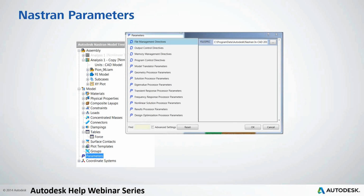Those are found on the model tree down at the very bottom. You right-click and you can edit, and it's going to pull up the parameters there. So it's kind of hidden away if you haven't seen this before. Like I said, it's all the way down the bottom, and then you pull up and you'll see we've got a bunch of different options here for directives, and then nonlinear solution parameters, solution processor parameters, things like that. So I'm going to go over a couple of these settings that can really help with a nonlinear analysis.